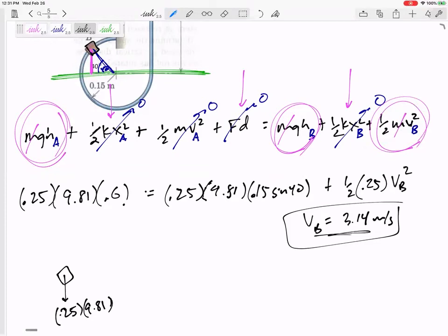And then we've got the normal force right there of the rod pushing on the collar. Now, if you've got a bead on a wire, a collar on a rod, it restricts the movement either way. So I actually drew it this way. It might be restricting it the other way. So for a collar, draw it one way or the other. Don't try to do both. If your answer comes out negative, that's fine. I think those are the only forces acting on it.